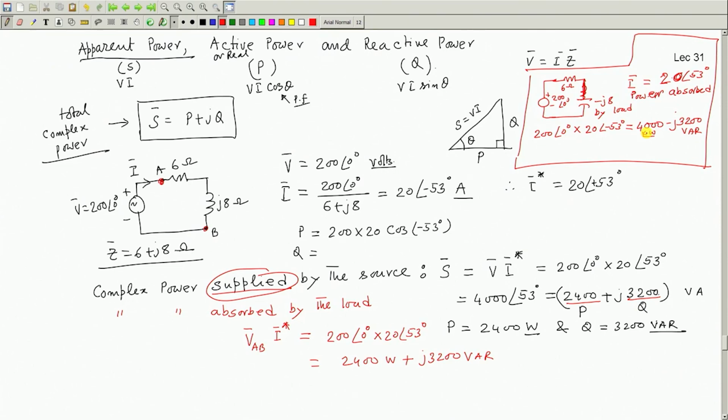So, inductive reactive power, we just interpret it as absorbing reactive power, but they are the same nature of power, nothing like that, but we make a distinction from the sign. If I say a circuit is absorbing 10 minus j50 watt and var power, I will come to know this is a capacitive circuit.